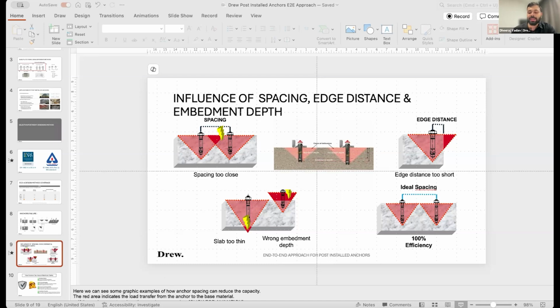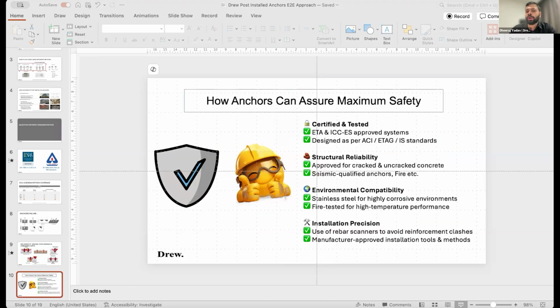and we utilize the right designing parameters as per these job site conditions to get the right selection and the optimized embedment depths and the different other parameters to it. There are also test reports available in the market. So basically, there are third-party test reports which evaluate the performance of anchor. So these third-party test reports, which are majorly followed in the market, are the ETA certificates.